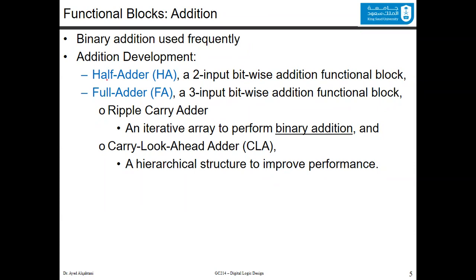After we discuss the half adder and the full adder in detail, we will use the idea of the iterative array to build the ripple carry adder and the carry look ahead adder. The main difference between the ripple carry adder and the carry look ahead adder is performance wise. The carry look ahead adder is better by an order of magnitude than the ripple carry adder.